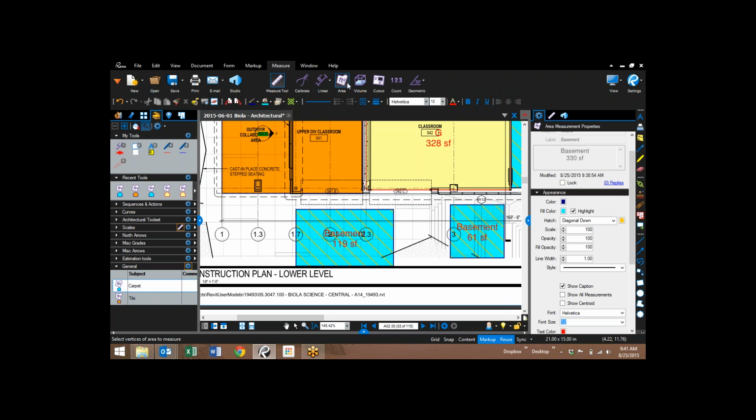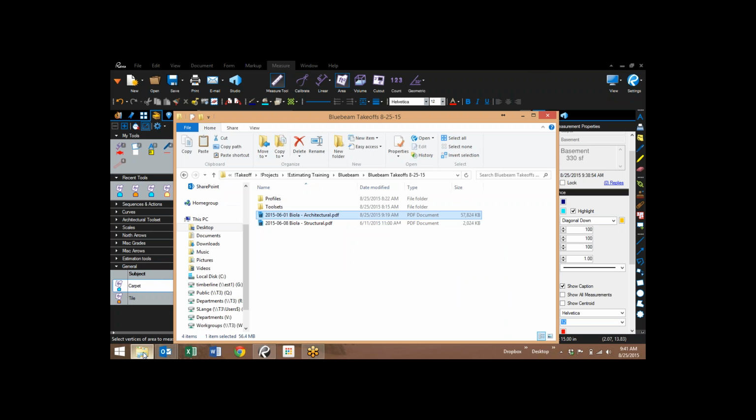You can use this button up here, the shortcuts, just to the area, linear, measure tools, but you're having to reformat every single time. So you save your formatted markups in your tool chest, and that's what you want. So now the great thing is you don't have to start from scratch. So let's go to the File menu and go into Tool Sets of that file that you downloaded from the Q drive.